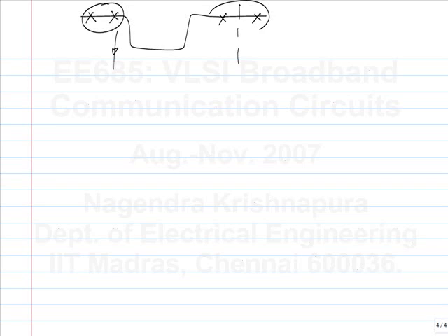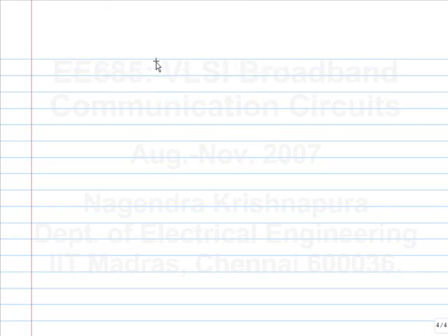The analysis of this is more difficult and we won't do it, but we'll analyze some aspects of it. Analyzing the dynamics of that is more difficult, just like analyzing the dynamics of an analog loop with a quantizer inside, that's a hard nonlinearity. Just like you are familiar with delta sigma modulators, right? So you make some approximations in analyzing that. So some similar things can be done here.